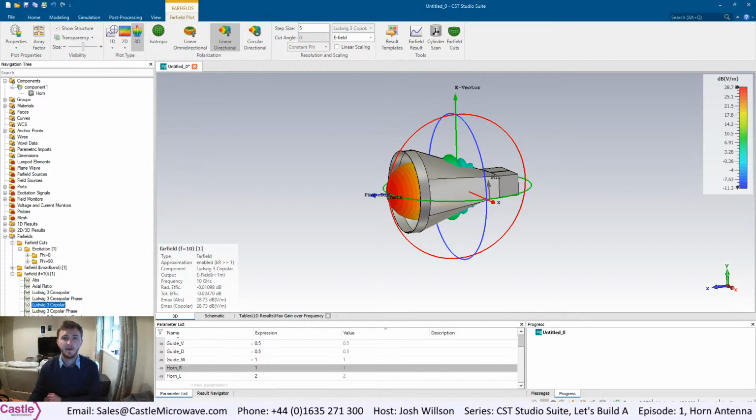In antenna design theory, the phase center is the point from which the electromagnetic radiation spreads spherically outwards, with the phase of the signal being equal at any point on the sphere. For a directional antenna, equiphasic behavior is required around the far-field main lobe in order to send clean data. When designing reflector antennas, which we might cover later on, the best position of the horn antenna to get the best radiation performance is to match the focal point of the dish with the phase center of the horn.